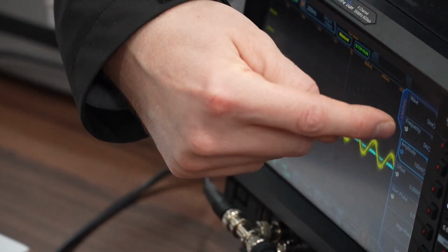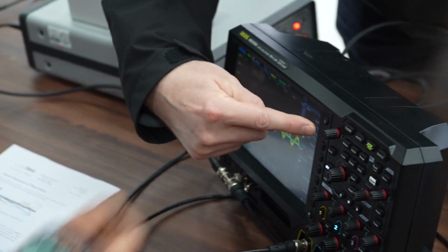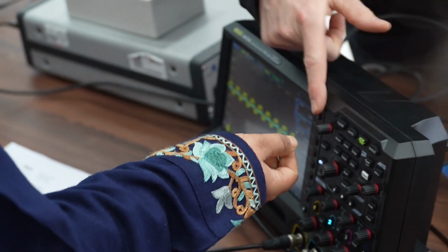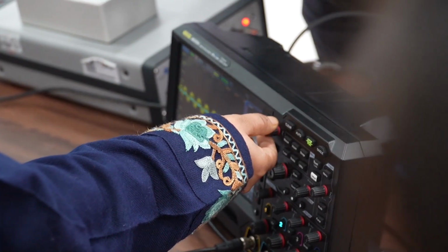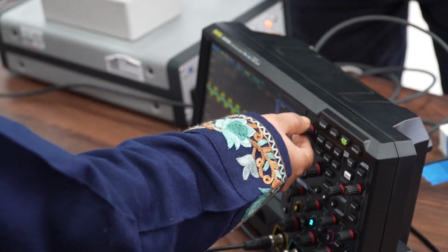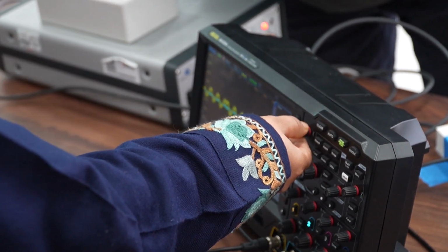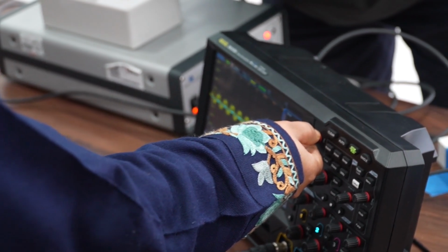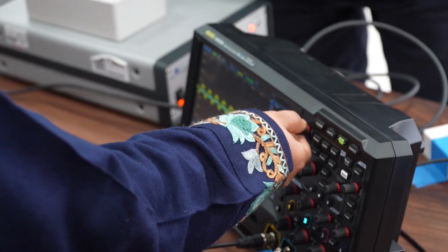Now you can do the following thing. You hit frequency, and now you use this and watch the frequency. Turn that and watch the frequency. Yeah, turn it. And now you go until you see that you reach the first eigenmode, and you will see that because the laser will do something. I don't see movement.